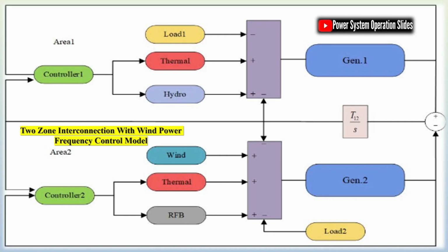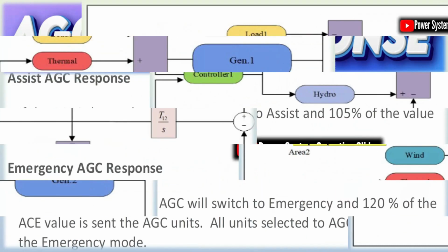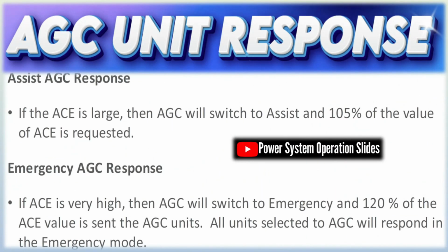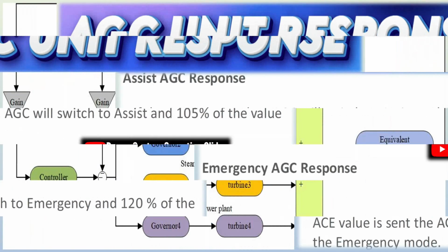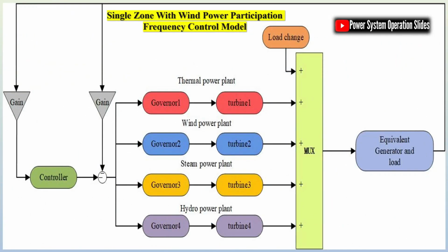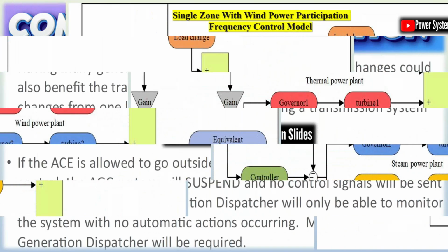Area control error, ACE, is the key error signal in AGC. It is computed as the combination of two components: the difference between actual and scheduled net power interchange, i.e., the difference in the tie line flows, and a term proportional to the frequency deviation from nominal, often weighted by a frequency bias factor. The AGC's goal is to drive ACE to zero, ensuring both proper power exchanges and stable frequency.